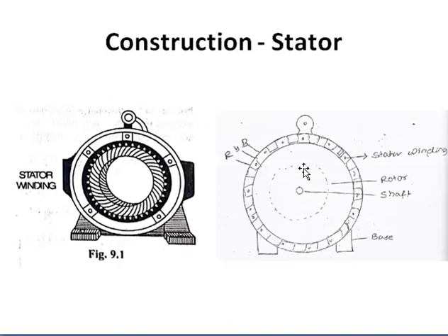And we know from Faraday's first law, whenever the flux linked with a coil or a conductor changes, EMF is produced. Now the rotor bars or the rotor conductors are experiencing a change in the magnetic flux, and that will result in an EMF induced in those conductors.